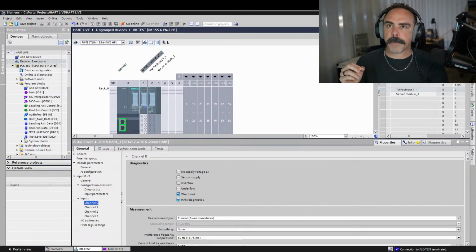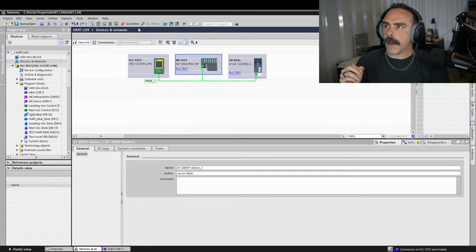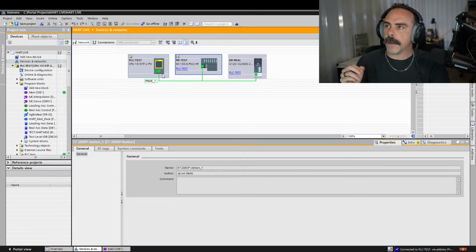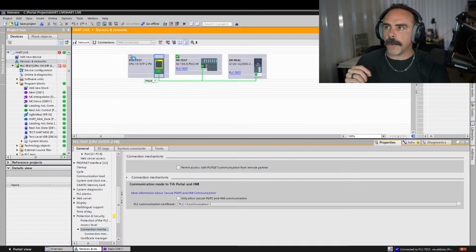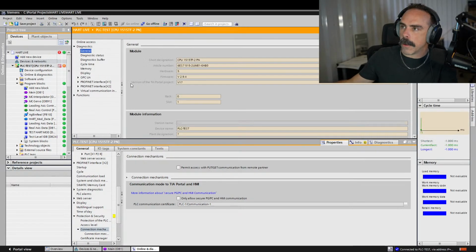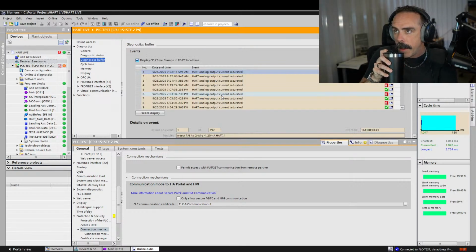Let me show you. We go online first, and I double-click on this little thing here, and it'll go up into here. I'm going to go into the diagnostics buffer, and it will tell you these diagnostics.